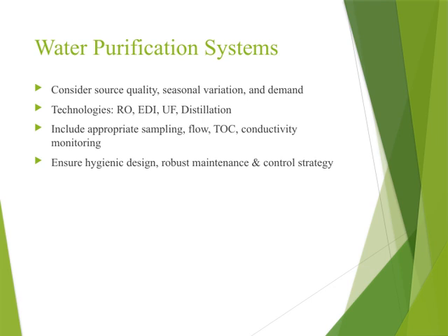Monitoring is also essential. We need to include appropriate sampling points, flow measurement, TOC, which stands for Total Organic Carbon, and conductivity monitoring, to ensure the water quality stays within specifications. These parameters help us catch issues early and maintain consistent water quality.